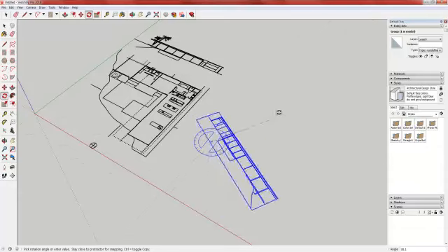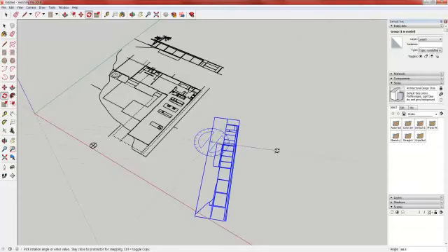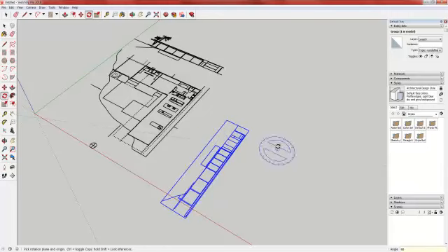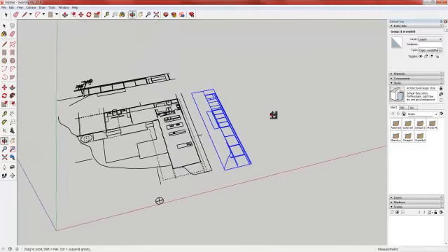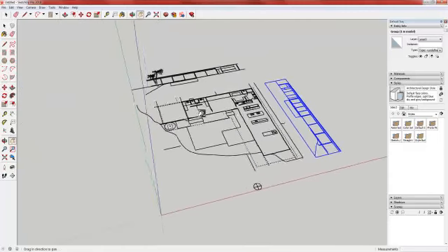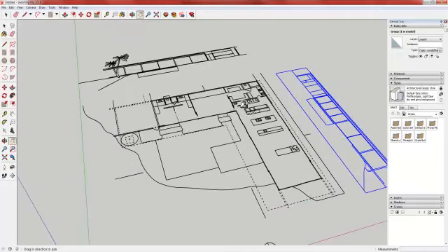Now I need to select my next level of rotation. For this project, we want this to rotate 90 degrees. You can see the angle in the bottom right says 66.9. I'm going to simply type in 90 and hit enter. It's usually a pretty good idea to use type-ins for your rotation angles. That allows you to be much more accurate. If you're a little bit off on your angle, it may look straight, but if it's not, it'll wreck your whole model.